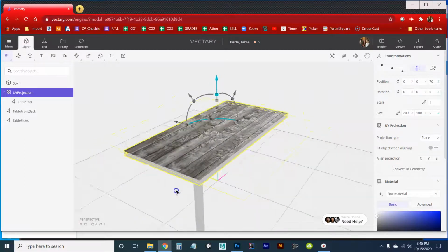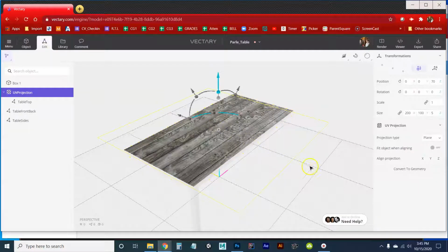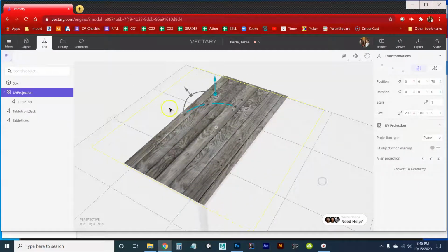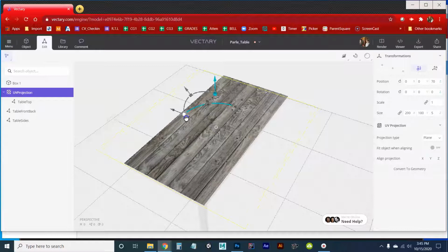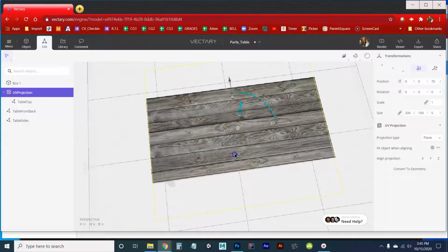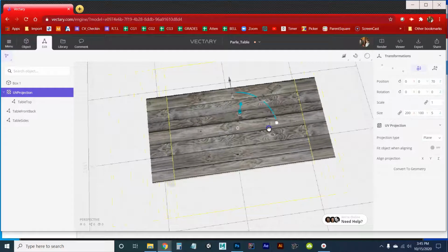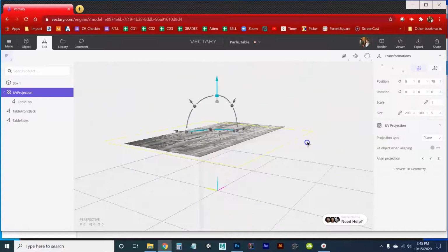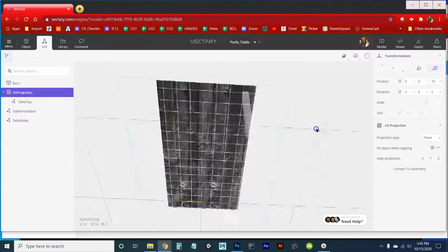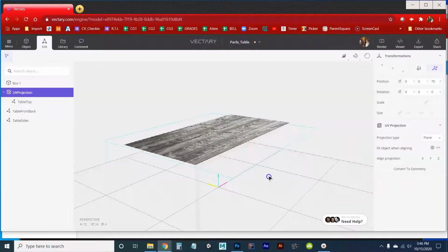So when we want to scale our projection, basically our UVs, we have to again go to edit mode. And then now you can actually see the manipulator move. We can play with squashing and stretching our texture. I'm going to squash it a little bit in this direction so that the edges meet up. And then if we want to, this should be repeated, but let's just play with it and see what happens. We're going to start stretching it, and then we're going to see lines there and repeated textures. So I'm just going to leave it at the default where it was, and that'll be okay. So when you did that, it worked on the top and bottom, and now you have to use that same idea on the other one.